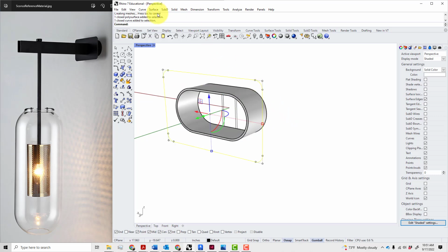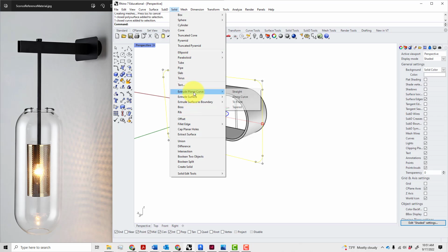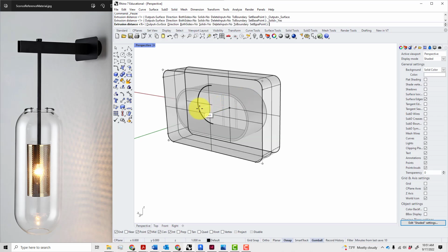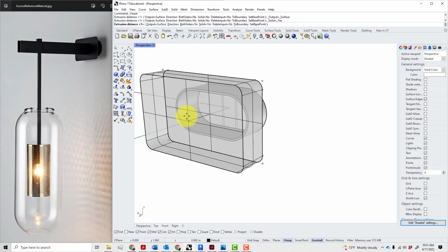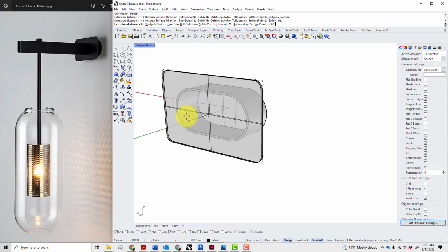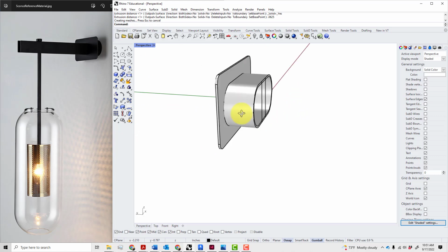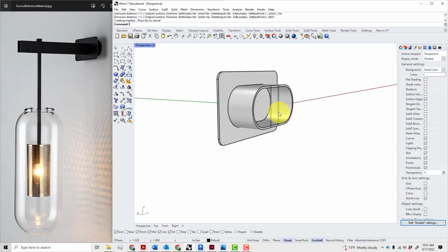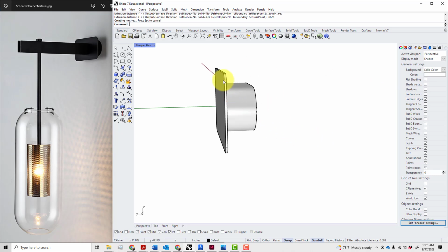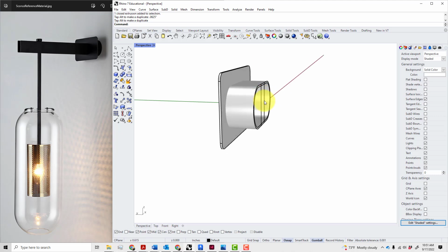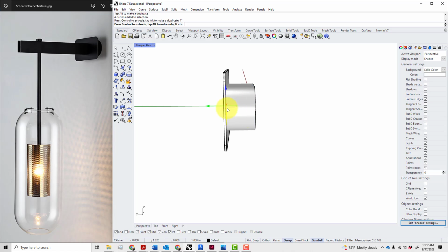So let's just do solid, curve, straight, and then we're going to give it thickness. All right, things are looking good. In fact, I extruded it this way, so I'm going to push that back so that this surface, not this side, is at 1 inch. And so I'm going to move these guys to 1 inch.